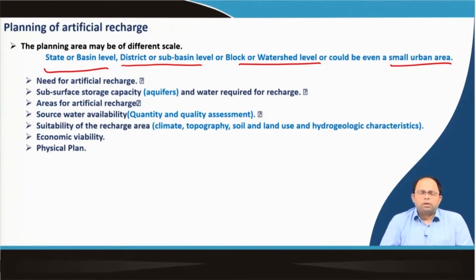This is very, very important, and you should learn this at the beginning: whenever we are talking about recharge, the first thing that we need to say is, is there a need for artificial recharge? Because with excess recharging, if we keep on putting water in the ground, eventually it will create floods, right. So, there is no point in putting in water which is not required. So, is there a need for artificial recharge? This is the first thing that we have to justify.